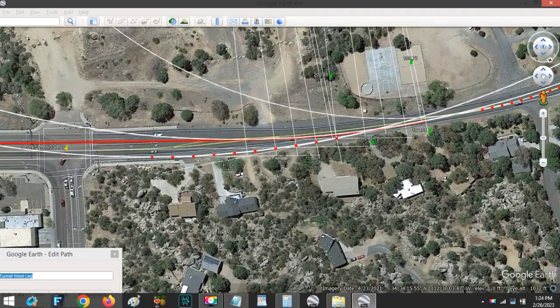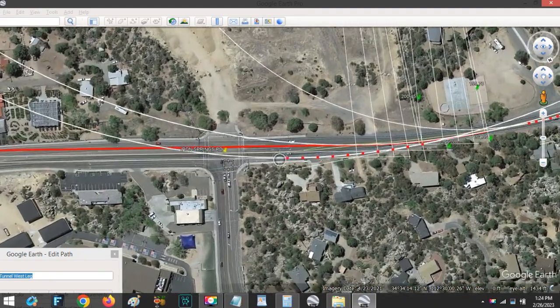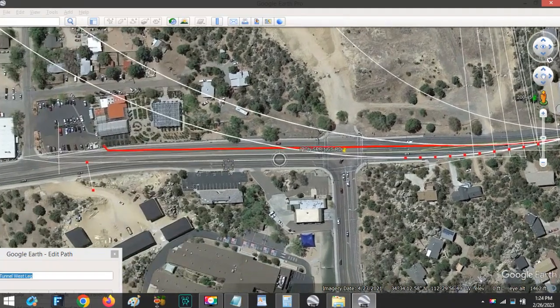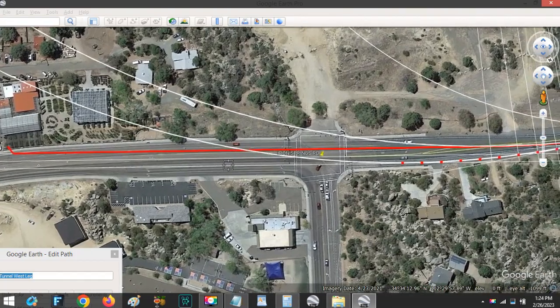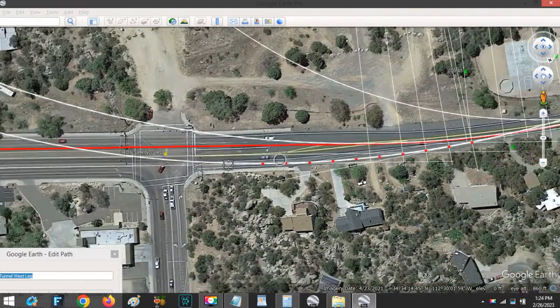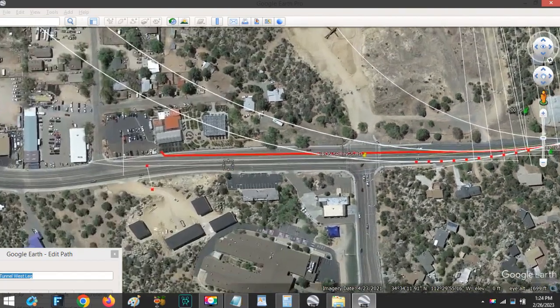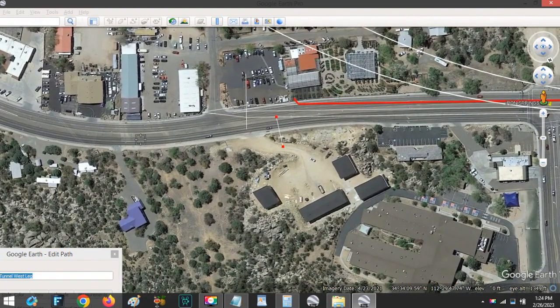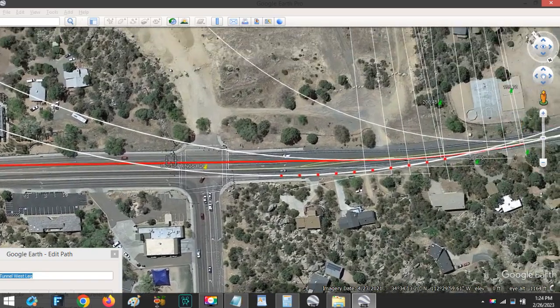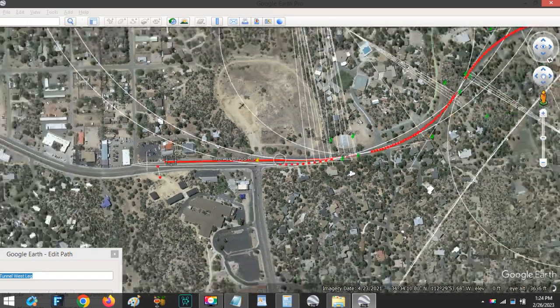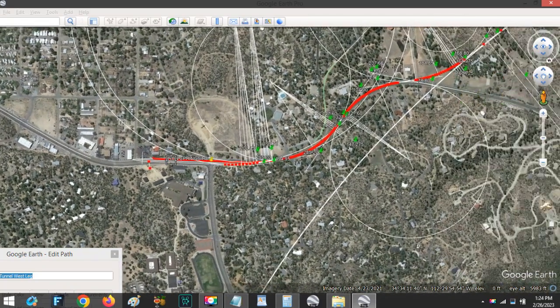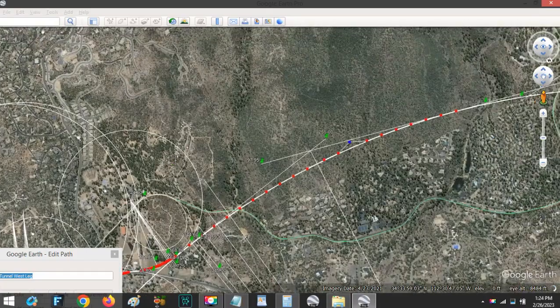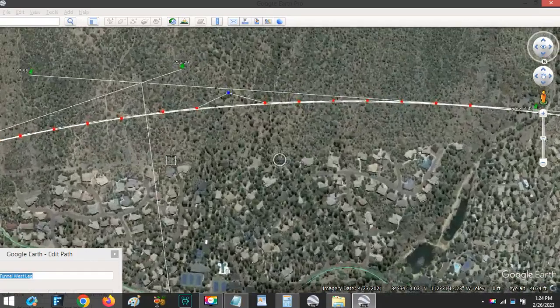Here we have a bigger circle with a 2,000 foot radius coming right into the station, and I won't be drawing the platform in this instance, but it might be nice if the other end is quite close based on this tangent here. It might be nice to have it a little tapered and rounded at the end. That'd be sort of a design characteristic that might be desirable.